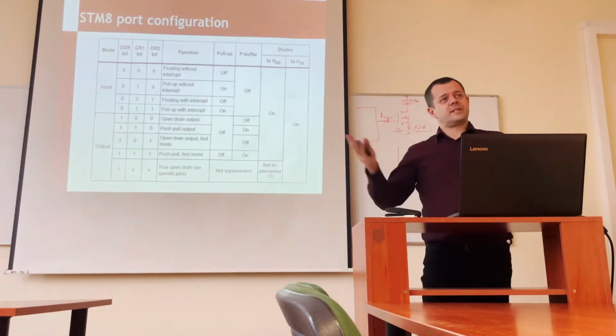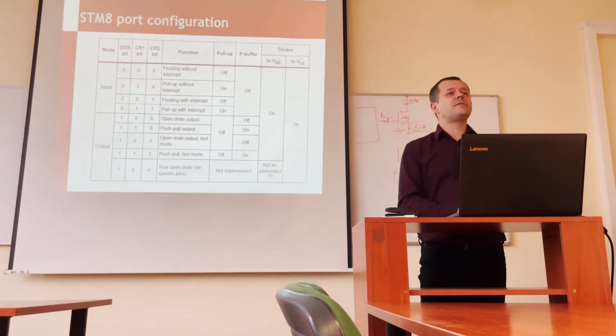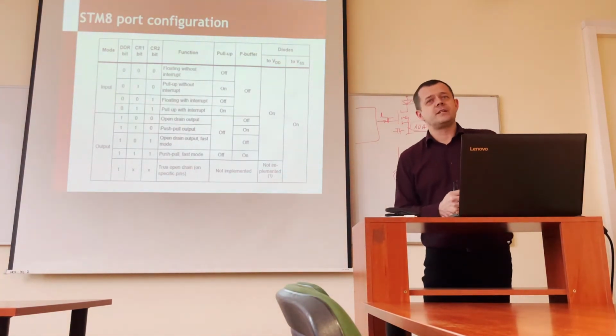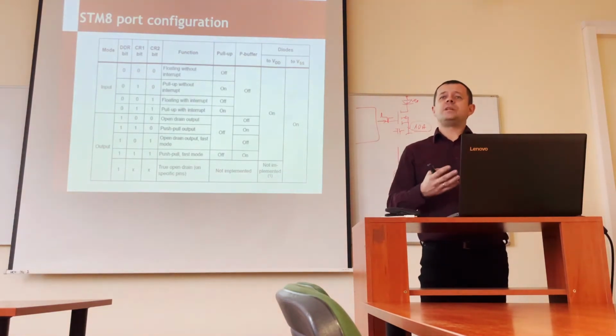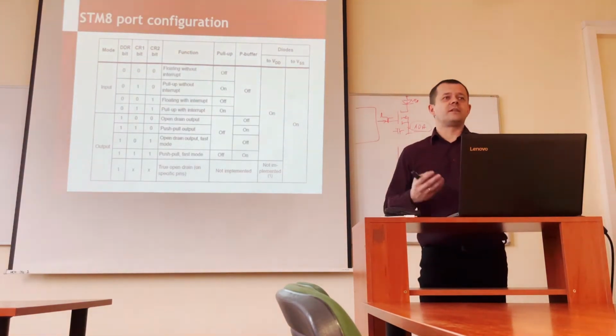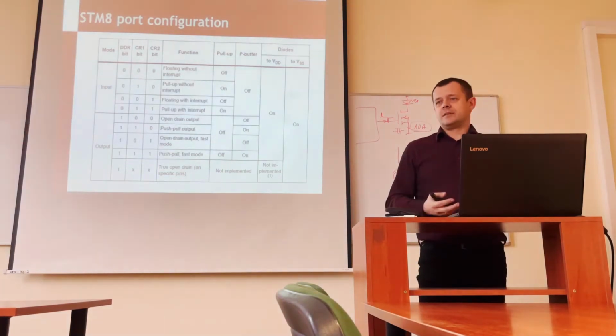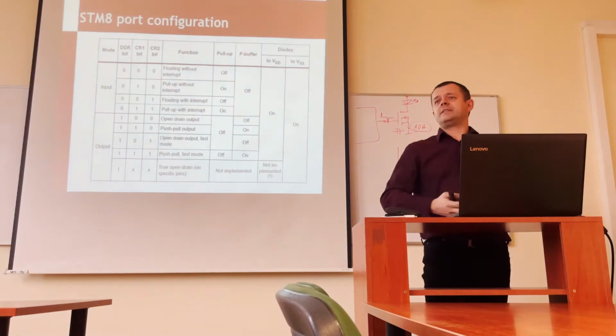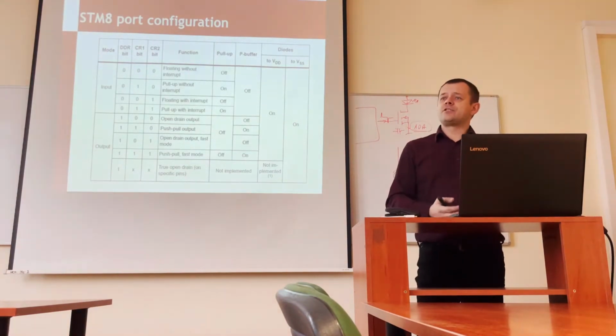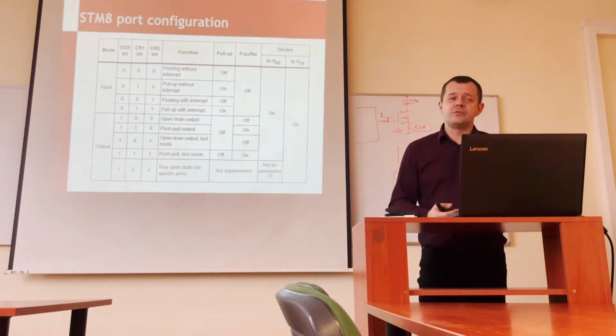Today, in microcontrollers, and the STM8 is an example, any pin can generate an interrupt. That's very convenient, because it's easier to make a PCB: we can connect a signal to any pin of the microcontroller that we have left and that is easy to connect, and then only in software we can configure which pin will generate the interrupt.